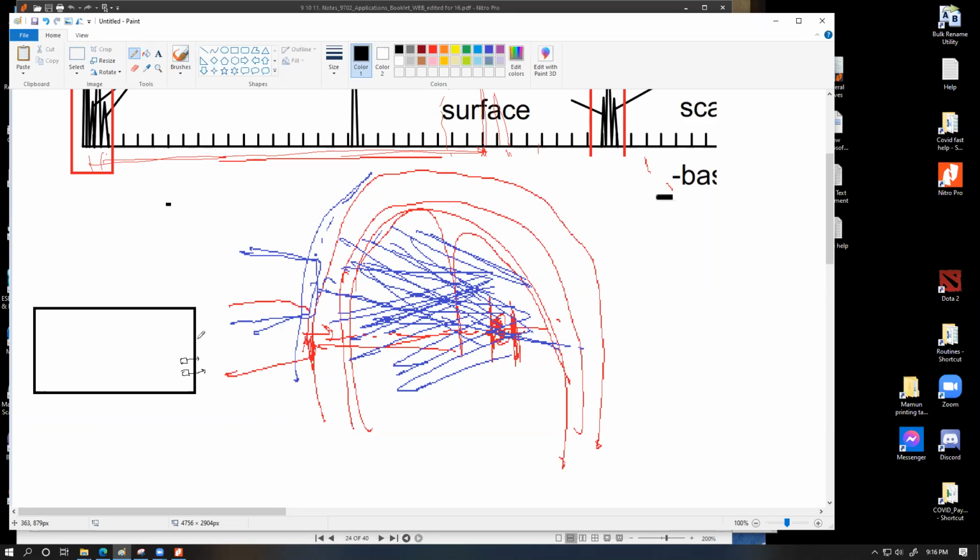So other than taking a lot of time by using only one single piezoelectric crystal to take a lot of images and eventually completing the whole image, the probe can have a lot of crystals which are aimed at slightly different angles from each other, so that we can make multiple scans using the probe at the same time, using slightly different frequencies for each of these individual piezoelectric crystals. That basically speeds up the process of a whole huge number of A scans. Those can be later merged together to produce the two-dimensional image.